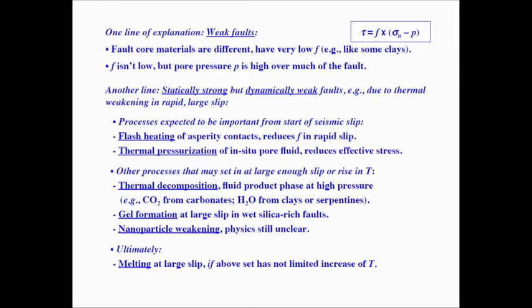But that's a possibility. Another possibility is maybe the friction coefficient isn't low, but pore pressure is a lot higher than we think. When we make elementary estimates, we usually assume that the pore pressure varies hydrostatically with depth, as if you had dug a well deeply into the earth and just let it fill naturally with groundwater. But that need not be the case, and there are scenarios of high pressure.